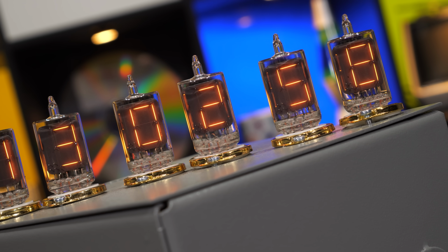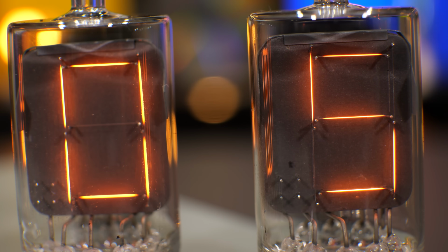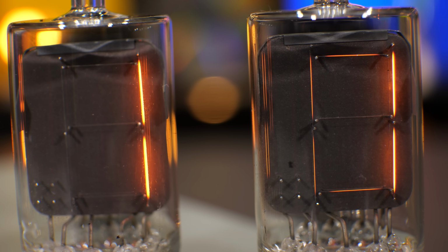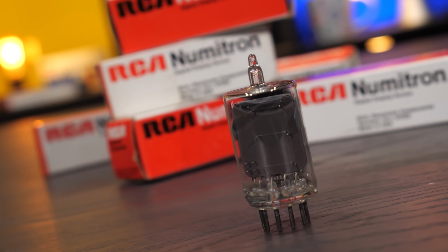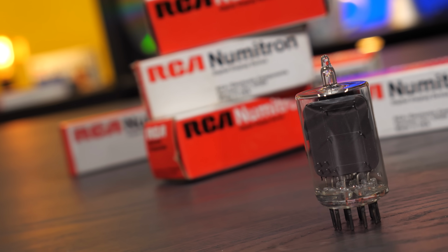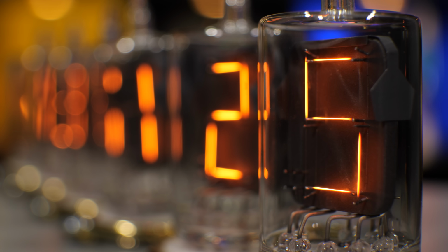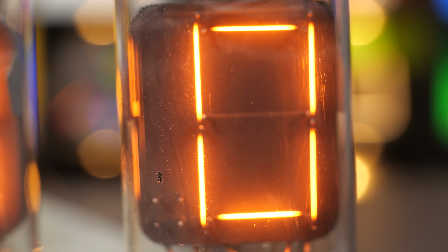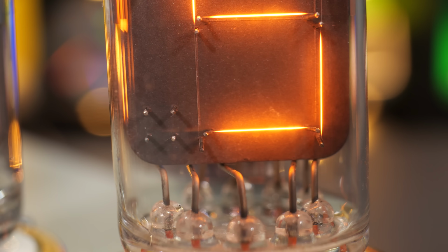First hitting the market in 1970, these really are just weird little light bulbs, but with 7 filaments. Each filament is stretched across little pegs on a support board, so they become the segments of a 7-segment display. Then that assembly got shoved into a standard 9-pin miniature vacuum tube enclosure. Just apply power to those pins to light up the right combination of those filaments, and you technically have a functional digital display device. Oh, and this model doesn't have it, but they were available with a decimal point option, which took the form of a tiny little X crossing these 4 pegs.